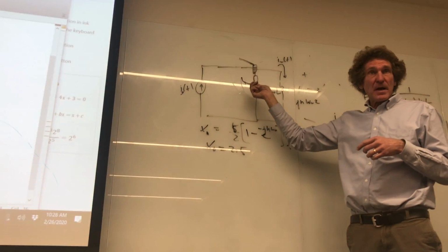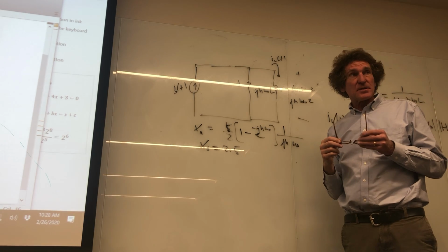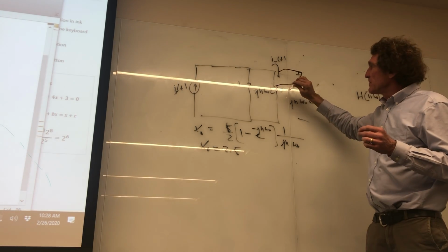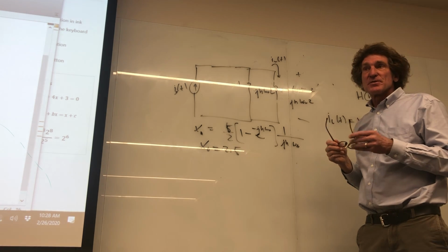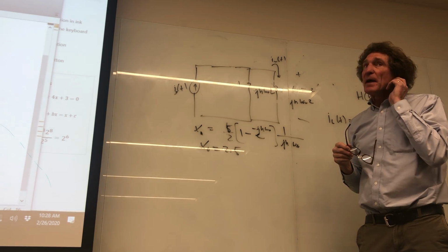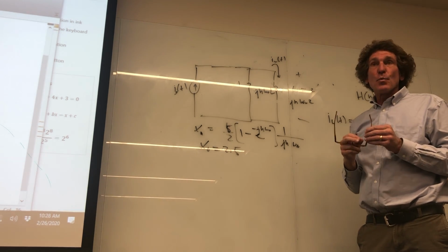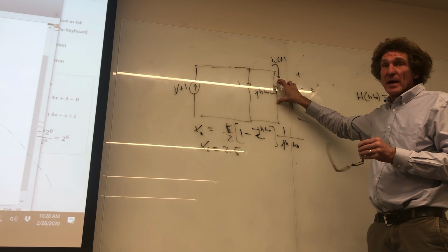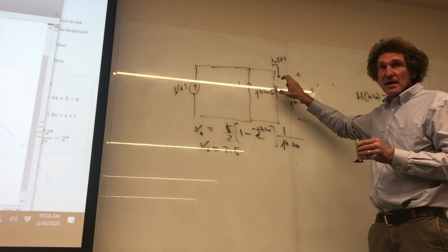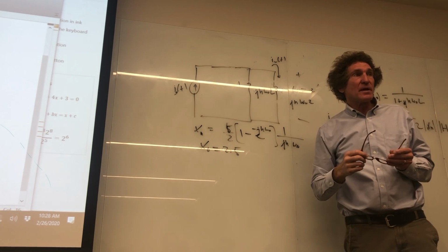You all follow me? Now you have a resistance in series with an inductor, right? Well, if you took the voltage off that inductor, you would see that you would have a high pass filter. But what would happen to the actual current is it would be a low pass filter and just allow the average value. And that's why inductors are used to get rid of ripple.